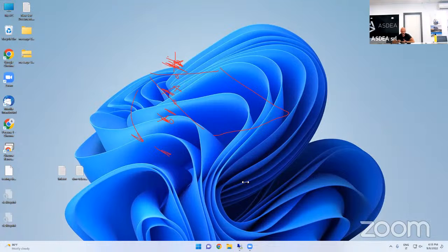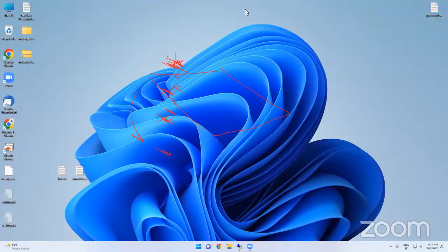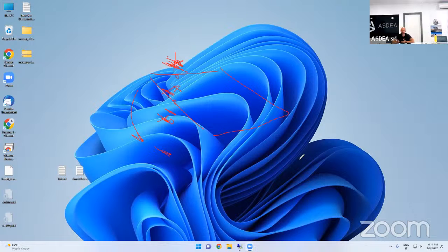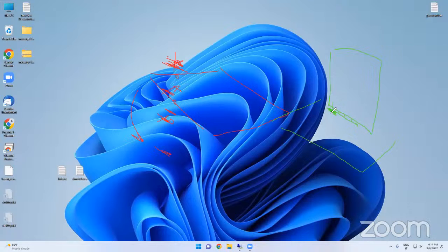Just the contact. Okay, well, basically, it depends on what kind of model that you want to use. For example, if you are modeling just beam elements, it's a nonlinear rotational spring. If you want to model three-dimensional elements, let's say shells, so you basically have this wall here, and you want to represent rocking here at the base with another object, then you need to use the contact element that you have in OpenSees. Now, contact can be only lateral contact, which for rocking is enough. Otherwise, you can have frictional contact if you want friction.